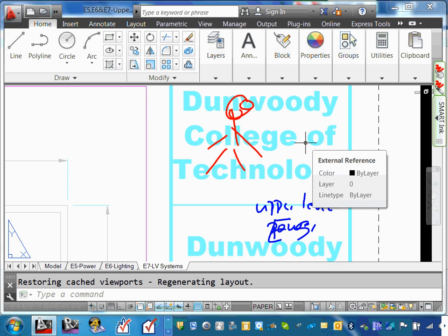So what I would like you guys to do later on is to go edit your title block. But we don't do it here. We open the file that we named the title block after we close all these. We edit it, we add a picture for you. You will add the name for your project right in here, like we did for the title block in Revit. We will do the same thing in CAD, edit that title block. When we're done, we save it. Then, when you open any of these files, it will tell you the title block has been updated. Would you like to load it? You say yes, and it will show all the updates. But I just don't have time to monkey around with that. Does that make sense? Everybody's good?